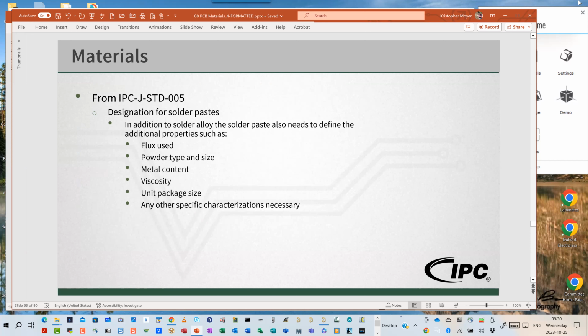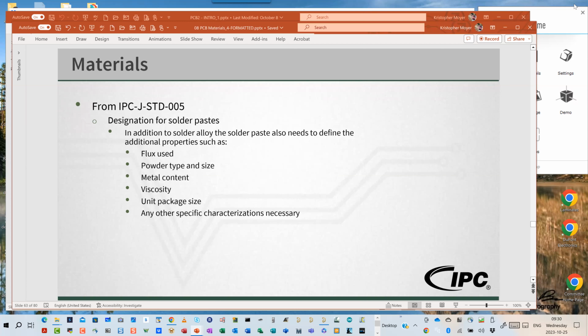Yes, question out there. I'm glad you pointed that out, because that's been a problem of mine for many years, trying to convince my company that it's worthwhile to clean our boards. Because they're using no clean fluxes? Yeah, and so the boards go into the PCBA testers, and it doesn't take long for the residue to build up on the pins, and it doesn't work anymore. Yep. And they're calling me to fix it, and it's been an issue, so I'm glad you mentioned that. I appreciate it. Yeah, no worries.